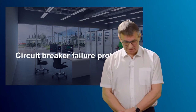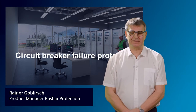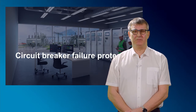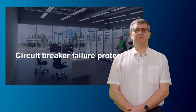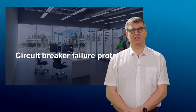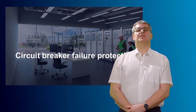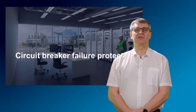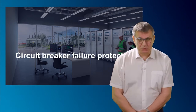So, as Nina already told, there's some backup functionality which is very important, and backup functionality which is really very useful to be used in a busbar protection device is the circuit breaker failure protection. The circuit breaker failure protection takes a very big advantage of the integrated disconnector image of a busbar protection device. But let's come to the details.